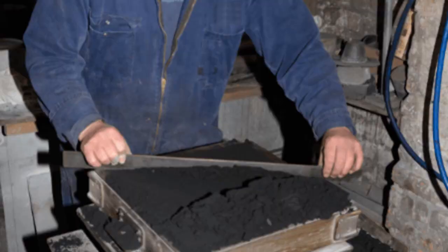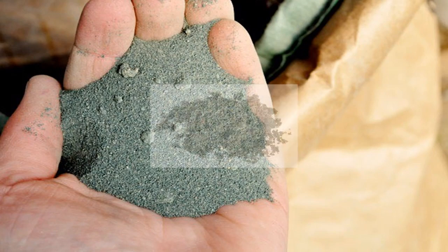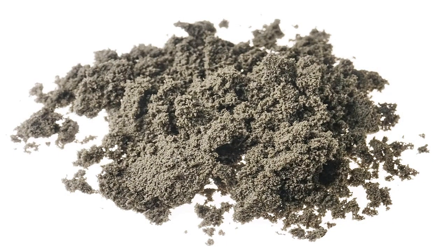Several factors are important in the selection of sand for molds, and certain trade-offs with respect to the properties are involved. Sand having fine, round grains can be packed closely and thus forms a smooth mold surface. Although fine-grained sands enhance the mold strength, the fine grains also lower the mold permeability.